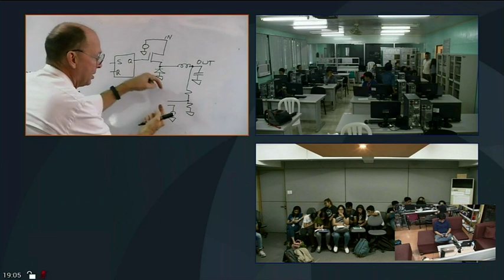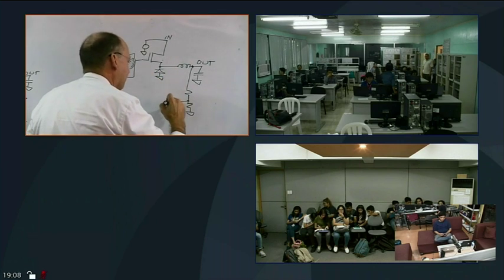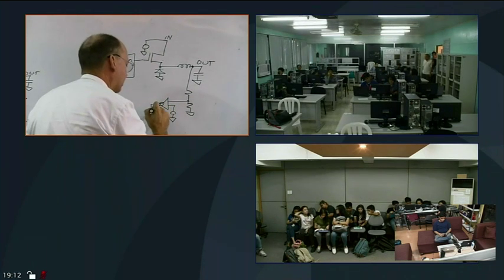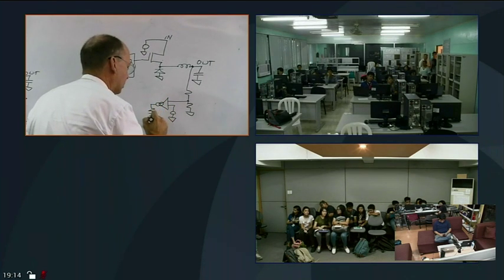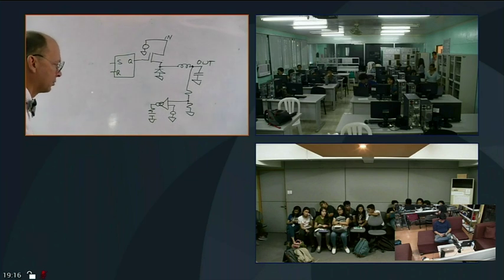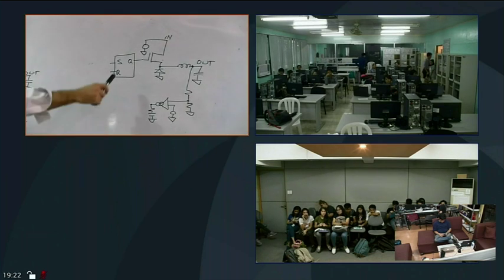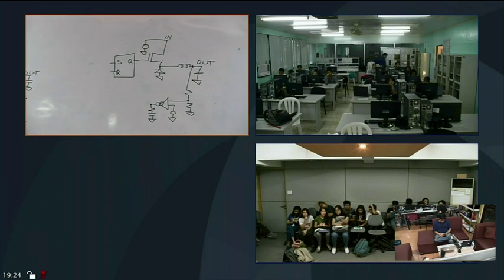The difference between these two is the error voltage, amplified by an error amplifier, and again, the amplified current is read out to a voltage with a resistive divider. So I again have an amplified version of the error voltage. So from there over, it looks the same as this. The only difference is that's a flip-flop, and that's a comparator. That's the only difference.